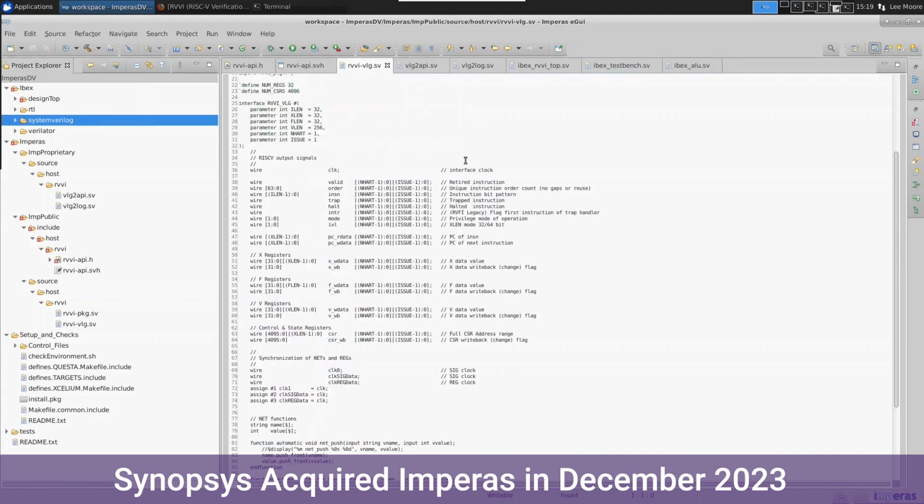Now the API is part of this to actually control the communication with ImperasDV itself, but we also have this SystemVerilog interface, which is how the transactions are described to the later part of the system. This is used in order to deconstruct the information that's coming from the RTL. It is based upon some earlier technology that was developed, and it's been enhanced for usage within environments which are multi-hart, multi-issue. So for each of the individual wires within this interface, you'll notice that they are dimensioned by the number of harts and the number of issues of each of those harts themselves. So if we had a hart within a processor core which could perform 3 issues in parallel, then we can describe that in this format here.